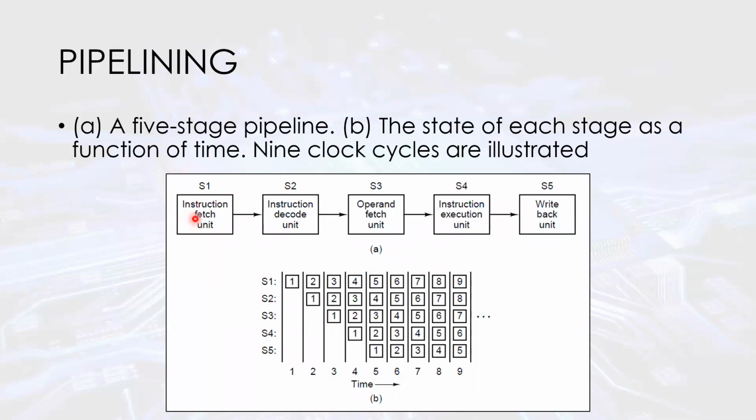Typically, we can break down a lot of those pieces that we saw in that basic microarchitecture, the IJVM, and do those in parallel. The idea is that we're pumping multiple instructions through our pipeline at the same time. So here, at time one, we start instruction one and it is being fetched, and then at time two, instruction one is being decoded.